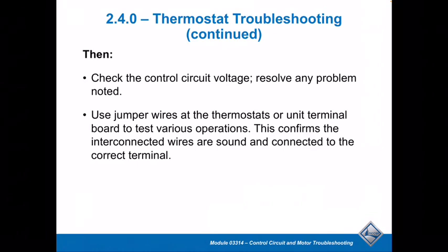Additionally, some of the things that we look at when thermostats aren't working correctly is, look at the voltages. What are the voltages? Are they appropriate? Is it what we should have? Most of the thermostats will be controlling 24-volt circuits. Look at the jumper wires. Are there dip switches? There's a lot of different applications where we would have done this. So find out if that actually works in the way we want.